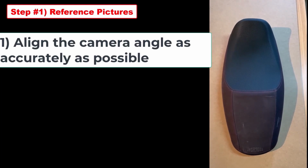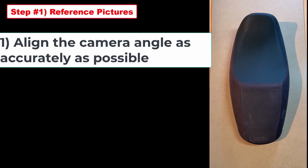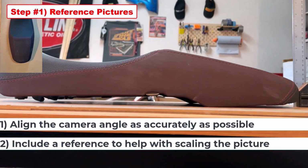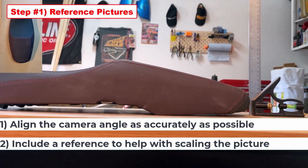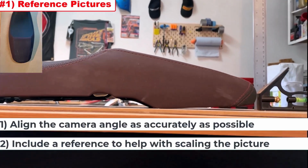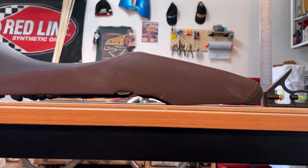So for this first one, I'm using the top plane, for example, and I try to get directly above and use the symmetry of the seat to align my picture. Tip number two is to try some type of reference for scaling. So you can use a feature with a known dimension, but in my right view, I just added a ruler to help scale it. And we'll see how to use that later once we get into SOLIDWORKS.